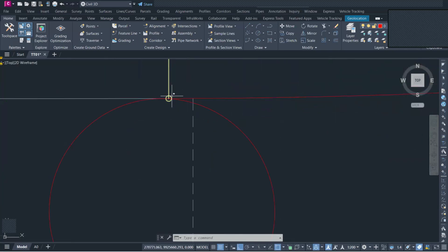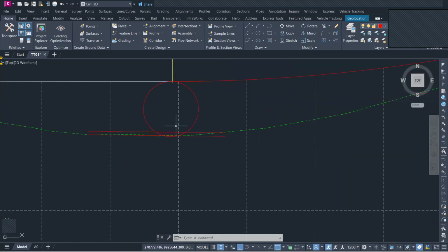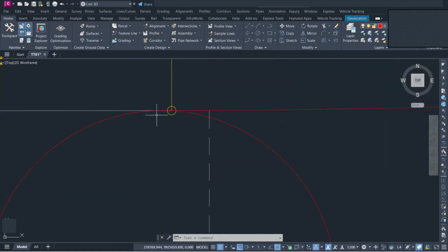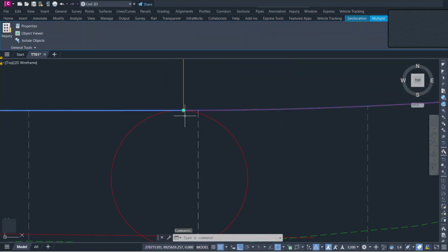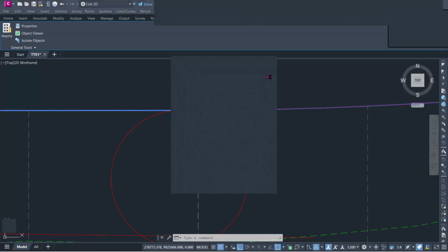So that then I can know the exact crossing point that we have at this point. So that I can know the levels at this point, and mostly it is the level of the top of the barrel. This is the top of the barrel. So the moment you have the top of the barrel, you can then know that my road layer now needs this amount of depth up there. So that is the approach that we use in the design of placing culverts.